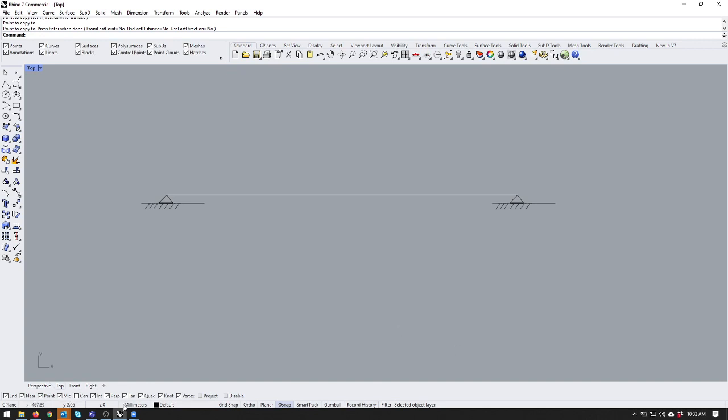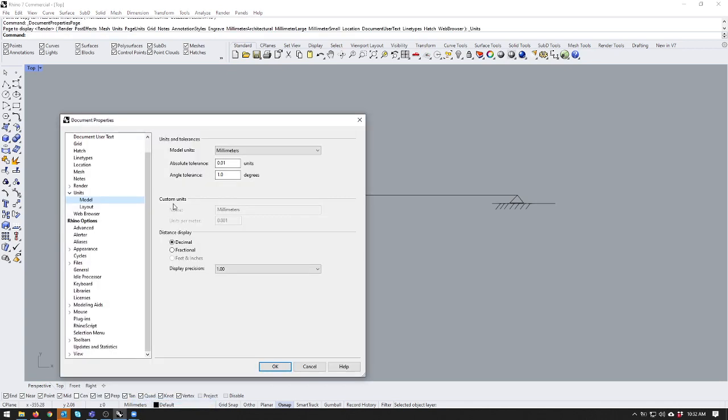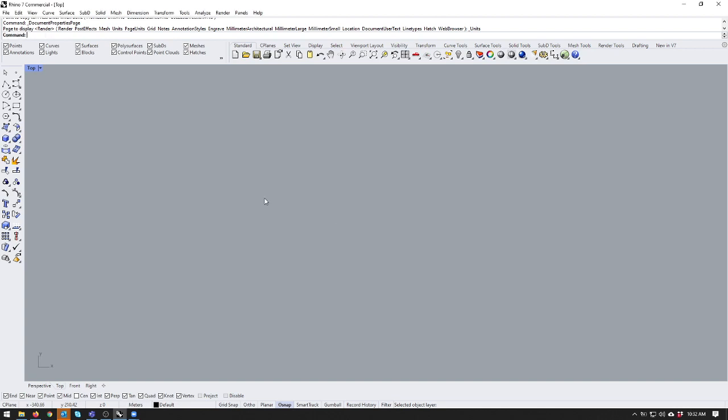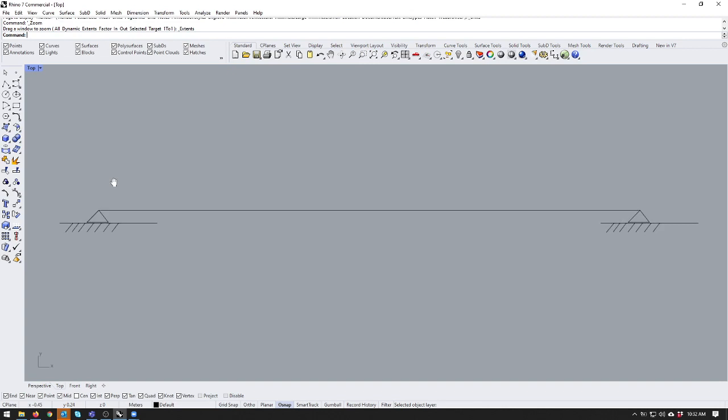So if we're doing any modeling with it, we need to make sure that at least the Rhino model is in meters, and our Grasshopper model is working in meters. Otherwise, you will have to do a bunch of scaling. And look, when you're troubleshooting these things in the future, and everything just kind of looks like it's going nuts, and everything's tiny, it's probably that you're working in the wrong scale. So just keep that as a note.